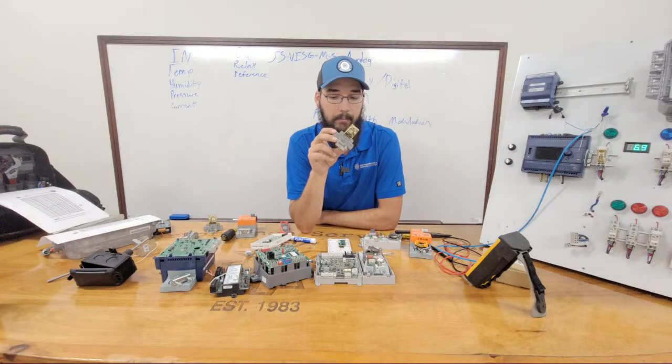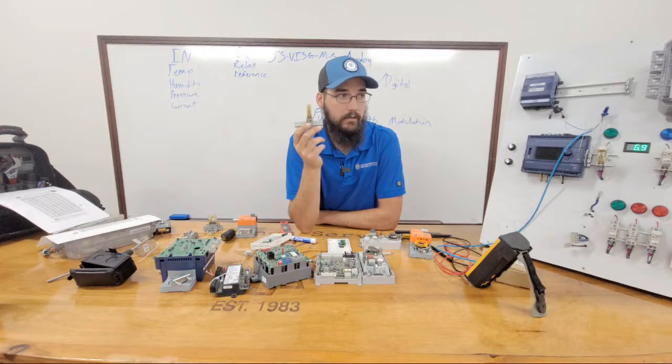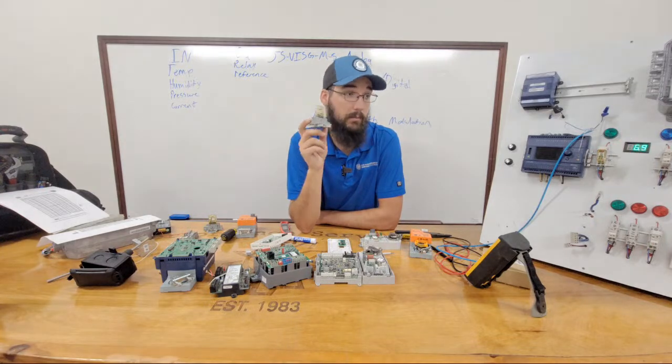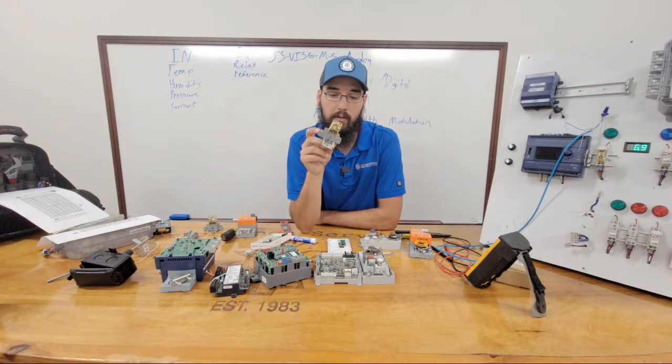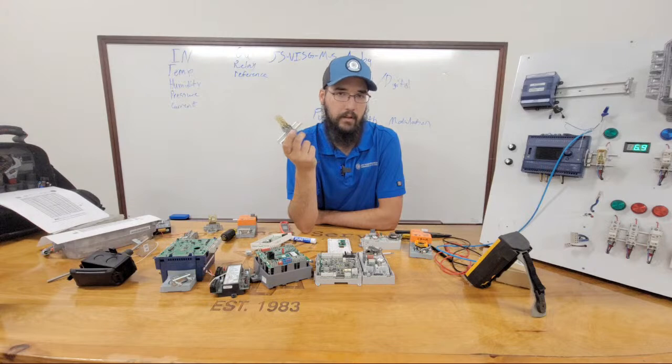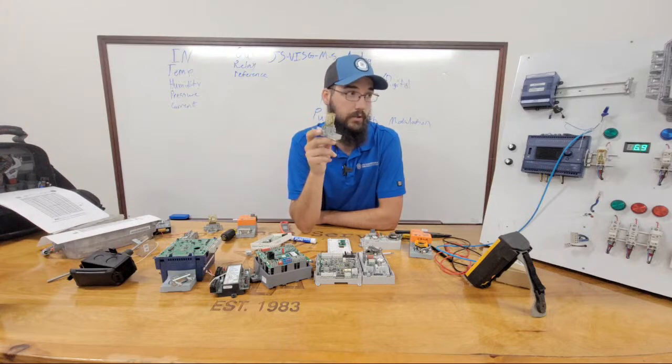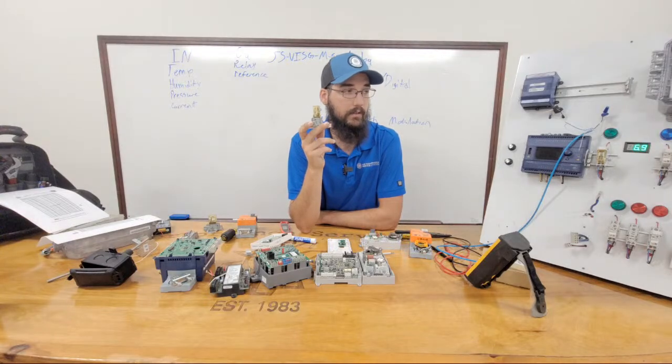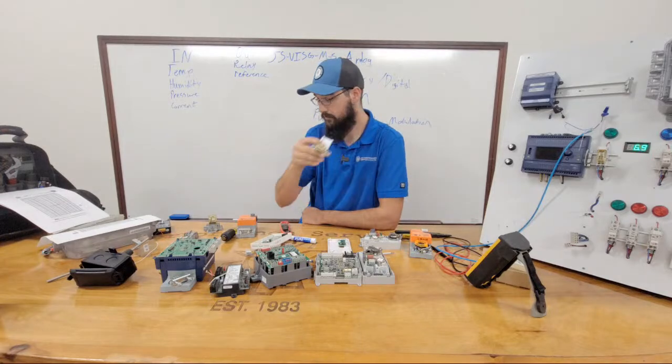These don't last very long. I don't know why. It's just the way they're designed, the make. Maybe they're just too cheap. Maybe the material they use. I mean, sure, you may get a couple of years out of it. Maybe. You might only get 6 months depending on what you use for it. I do not use these to control loads. We want to use these as pilot duty devices, not load duty.